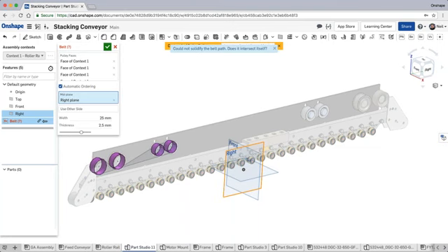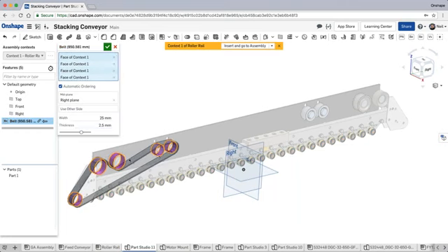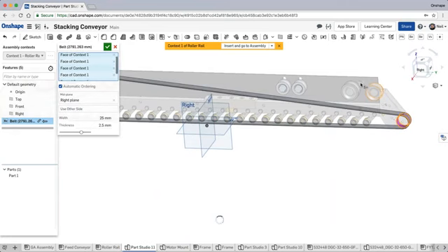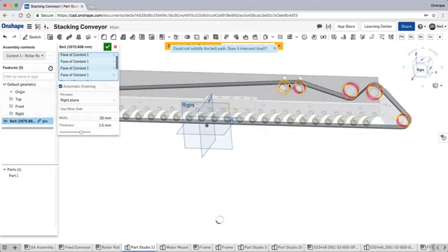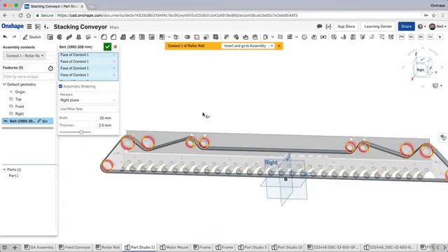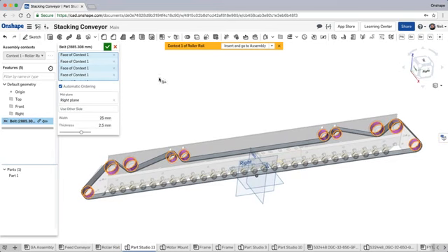And okay, what we'll do is continue adding more faces. And what you'll see is that those are crossed over, and that's simply because it couldn't find a solution with those 4 belts. Now you can see it's starting to build the geometry that we need. Likewise, we can come over here, start adding these belts in, and it knows based on the order and how many belts there are that there's only really one solution to this problem. You can flip them over, but this is an example of a custom feature built within Onshape.